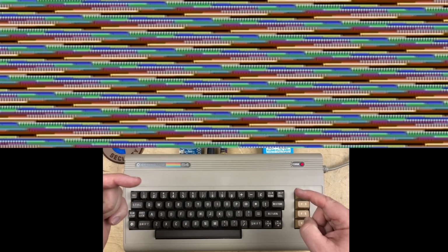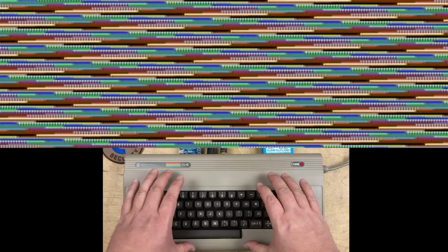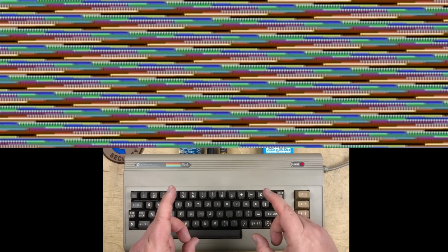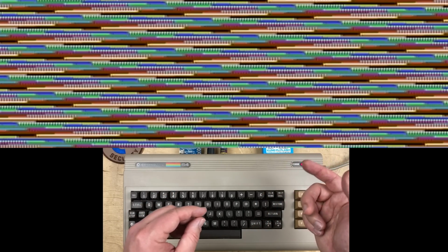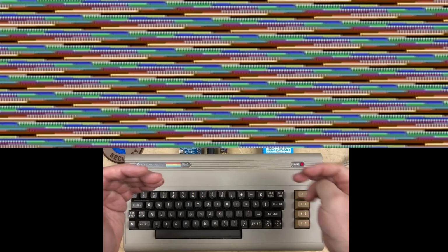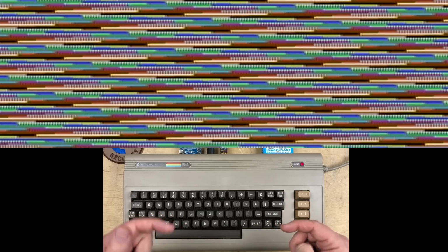Then it goes to the next scan line, draws from left to right, all the way down. Now, on an NTSC machine, it does 263 scan lines like that. And on PAL, it does 312, but that's at 50 hertz, 50 frames per second. But no matter what, they all draw from the top left, one line at a time, from left to right, over and over again. Okay, so it's a repeating pattern, but it looks kind of chaotic.